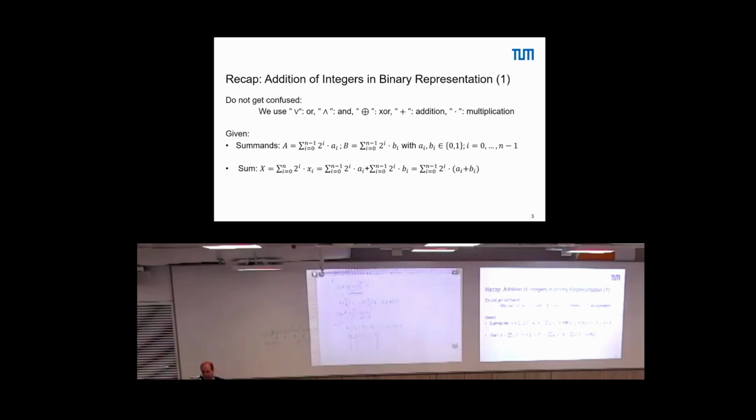So, now, something unclear? All good? Now we try to write this in that form. If we want to have a 0 represented as 2 times C0 plus S0, C0 should be 0 and S0 should also be 0, right? If we want to have a 1, then S0 should be 1, C0 should be 0. And if we want to have a 2, then C0 should be 1, S0 should be 0, right?